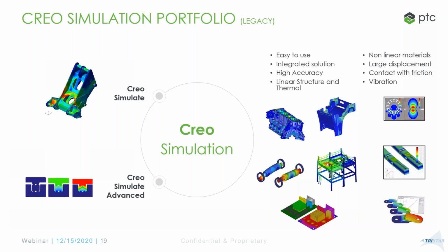There are two extensions, and some of our customers who just need linear analysis, they would use Creo Simulate, and those who required advanced nonlinear analysis, large deformation, contact, or even shaker table tests mimicking vibration analysis. They want to bring in a PSD plot and do some high-end vibration analysis there, or in time, they want to do a half sine sweep test or a shock analysis. Those types of things are available in Creo Simulate Advanced, right? So those used to be the two options we had, and we had a Fatigue Advisor to do some fatigue analysis as well.